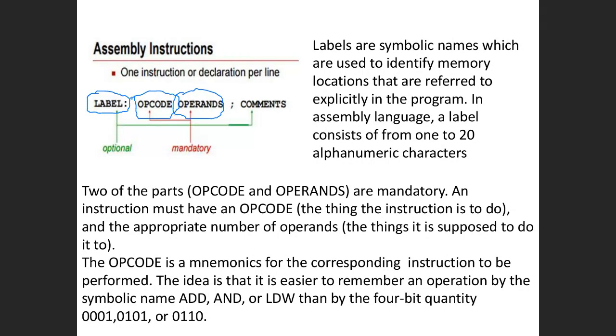This I already said, and after the semicolon we can write our comments. For example, if we write MOV AL, 07H, you can put a semicolon here.